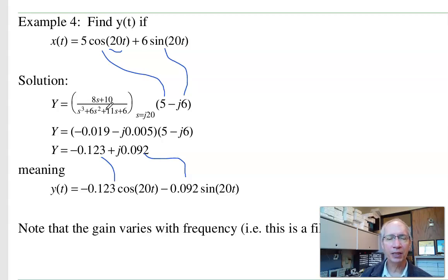You use that in Circuits 2 and electronics to design different types of filters. I can build a low-pass filter, high-pass filter, band-pass filters, like for your subwoofer. The subwoofer has a filter that passes low frequencies to the woofer, everything else to the mid-range and tweeter. Anything described by a differential equation is a filter.